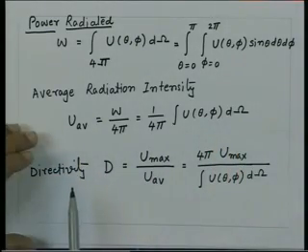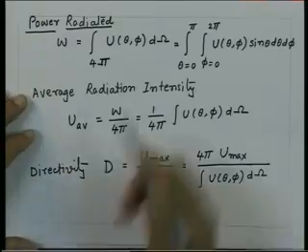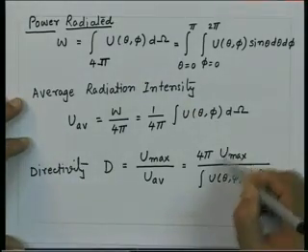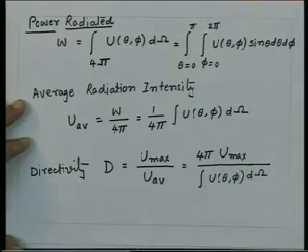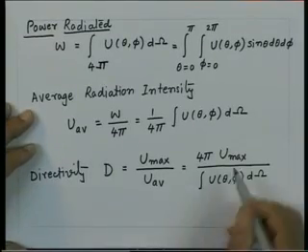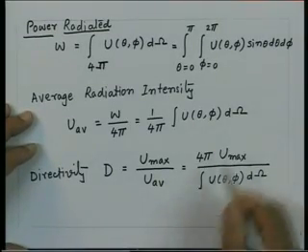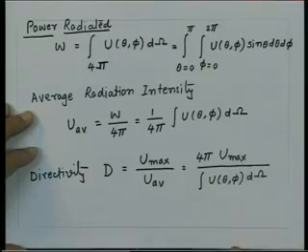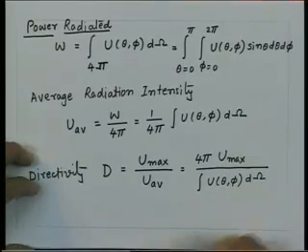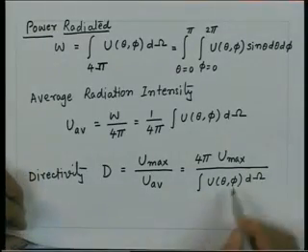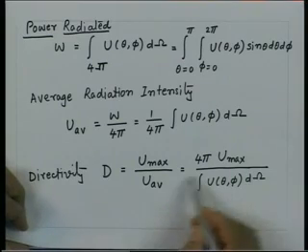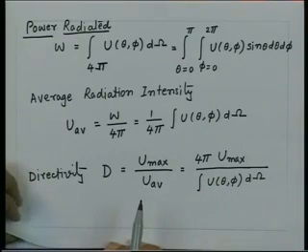That is what the Poynting vector is. So, whatever the proportionality constants are, they will get cancelled, because you are taking a ratio of these two quantities. So, I can replace U max by the square of the maximum electric field, and replace this by the square of the electric field in a general theta phi direction and find the integral over the total solid angle.